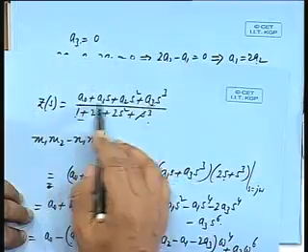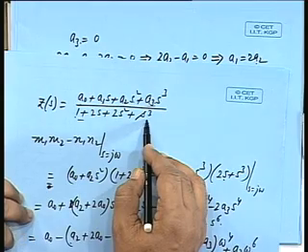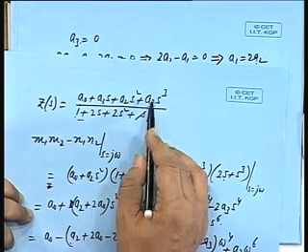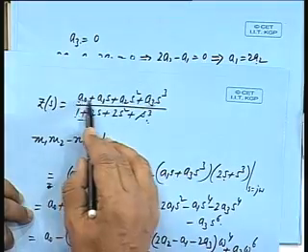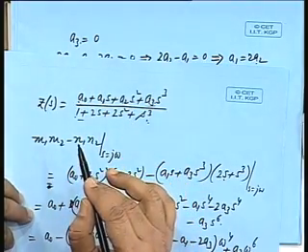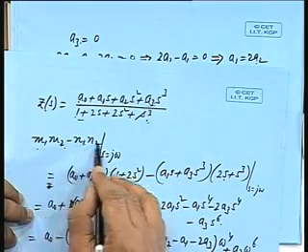So we started off with the denominator polynomial, made a substitution of omega squared equal to minus s squared, got the roots of the total set, that was m2 squared minus n2 squared. Then find all the roots, take the roots of the left half plane, form the polynomials, write in the polynomial form, and then assume a numerator of maximum power of the denominator. Then find out the numerator of the even part from this relation m1 m2 minus n1 n2.